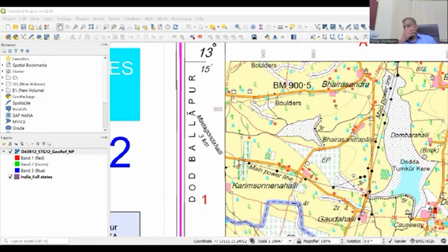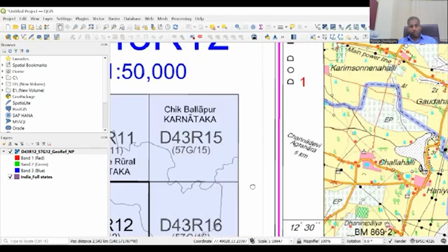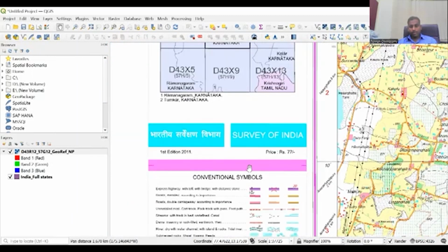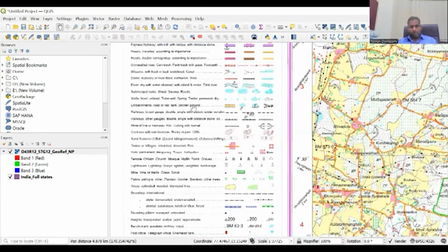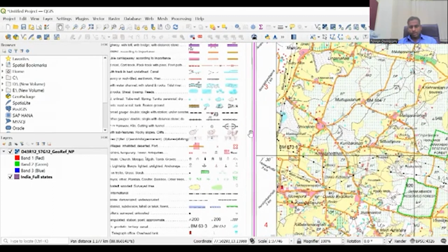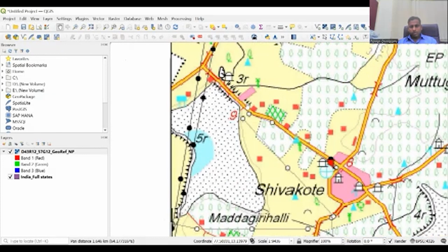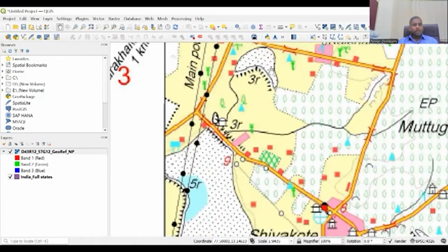So what we will do here is, we have seen multiple legends, but we are going to only use tube wells. So I'm going to come down and then go to the same location where we had tube wells, and then I'm zooming in, right? So here is where I'm going to zoom in, and I'm going to make a shapefile. So now the first one we're going to make is points. So the points, how I'm going to make, you have this plus mark in yellow. So you can hover your mouse on top of it. It says new shapefile layer.